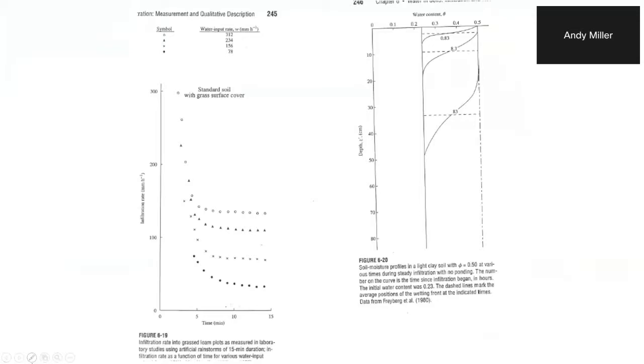Because we're going to look at other evidence that suggests that over time, as you add water, the infiltration rate changes, and it usually does approach asymptotically some final value, which is often the saturated hydraulic conductivity of that layer itself. There doesn't appear to be one saturated hydraulic conductivity in here. This seems to be responding to the application rate.